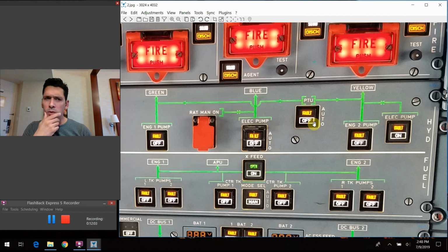And the reason that we do this is you don't want to have the pumps ever be in a situation where they call it cavitating, or it's really kind of hiccuping. So if there was some interruption of fluid, this would be bad for the system. We get air in the lines, and it would cause problems for us. So when we talk about this air pressure in the reservoir, that's exactly what it means. It's the head pressure on the hydraulic fluid itself.